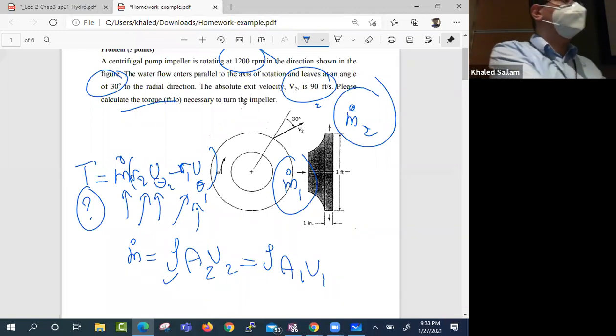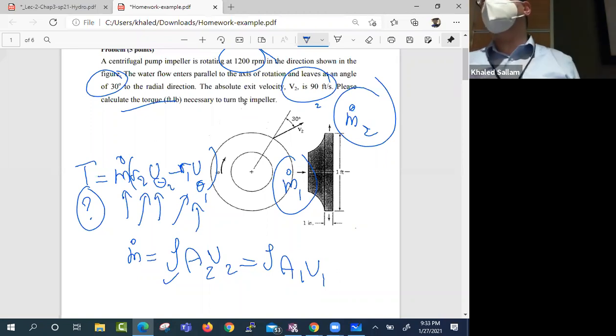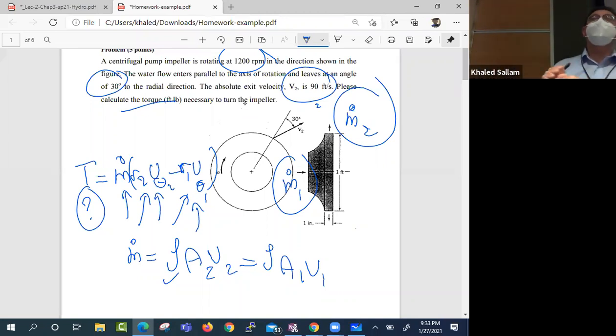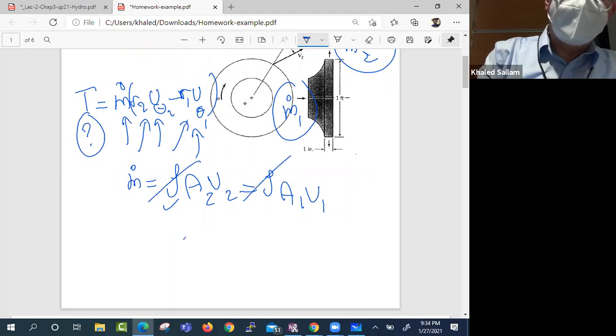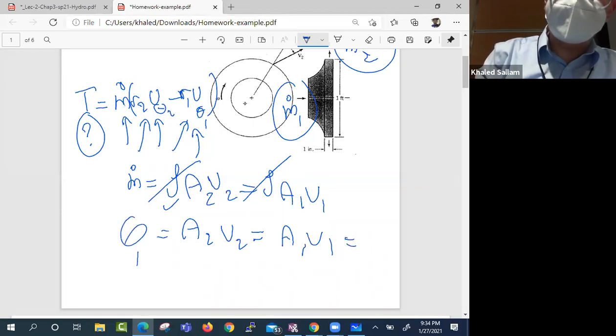It means that if you think about the fluid as billiard balls, the moment you squeeze a billiard ball in, a billiard ball will have to pop out from the other side, because there is no space. So not only m dot equals m dot, the volumetric flow rate is the same too. Q1 is the same as Q2.